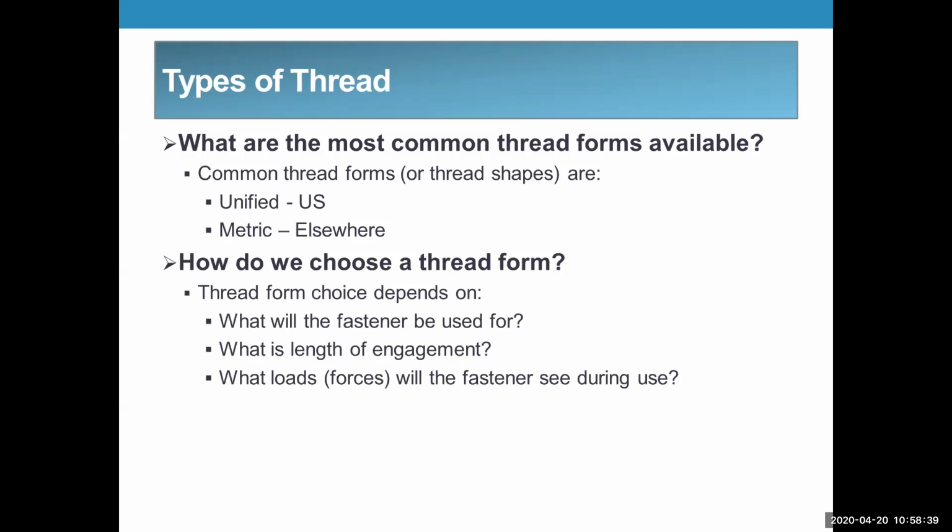And we're only talking about small deflection, right? You usually can't have more than about 1/8 of an inch deflection in a steel form, whether it's an I-beam or a tube or an angle or whatever it is, before you're creating so much stress that the material might yield at some point.